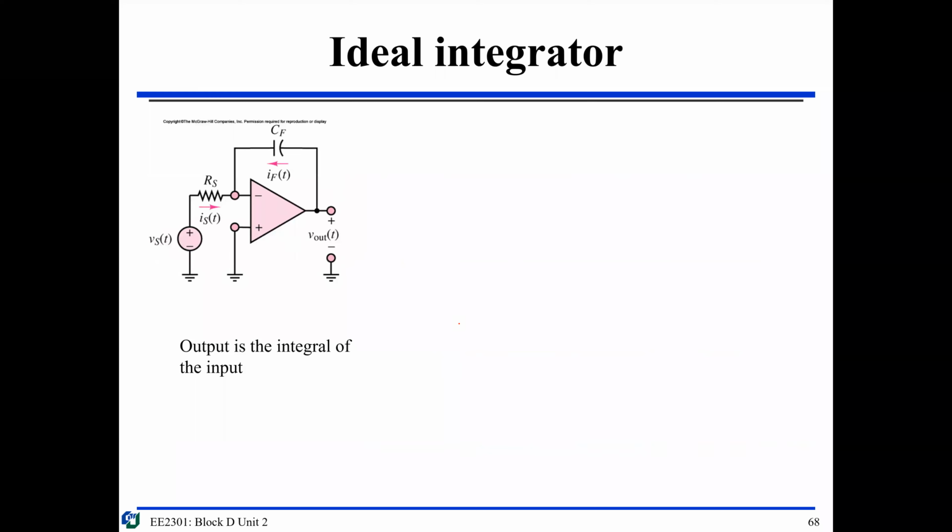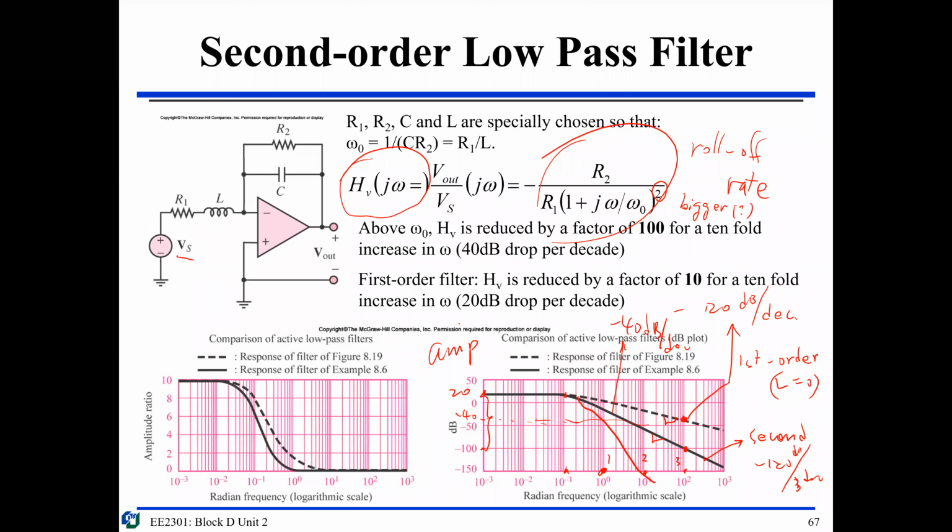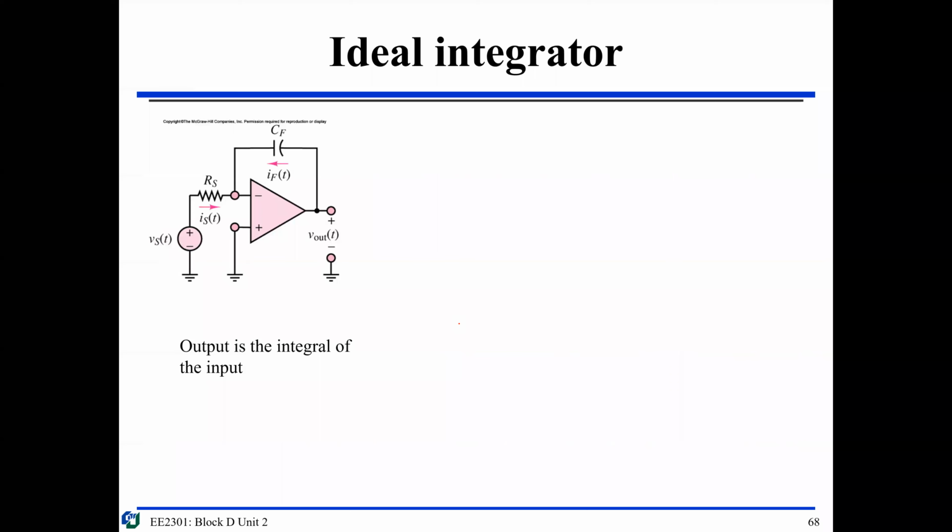All right, before we end, we are going to finish by introducing another 2 important circuits that do differentiation and integration. We learn the integrator first, because this is widely used in op-amp circuits. So this is called an integrator. The integrator is like a low pass filter.